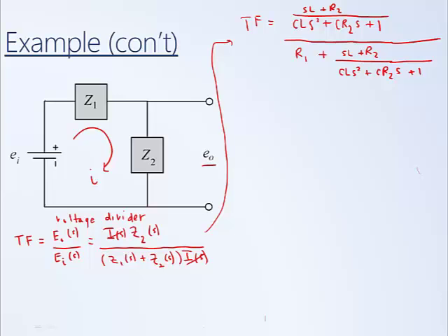In essence, this is the transfer function, and we could stop here. But in general, we would like to clean up our transfer function a little bit so that it's easier to understand and compare. And so basically, I would like you to get your transfer functions into the form of a single polynomial divided by a single polynomial. So in essence, we want to get rid of these fractions here.